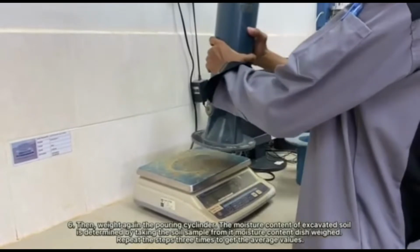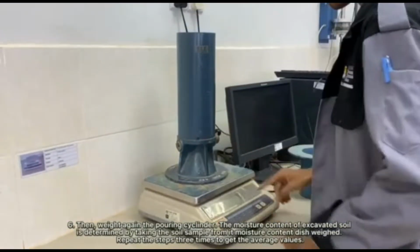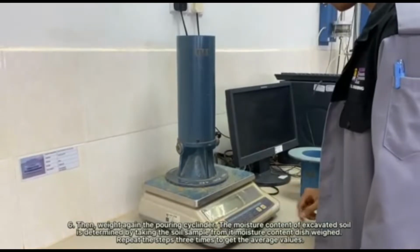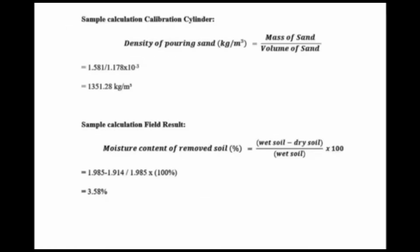The moisture content of excavated soil is determined by taking the soil sample from it into a moisture content dish and weighing it. Repeat the steps 3 times to get the average value. This is the data for the experiment, which is part A calibration stage and part B field result. This is the sample calculation for calibration cylinder, which is density of pouring sand, and sample calculation field result, which is moisture content of removed soil.